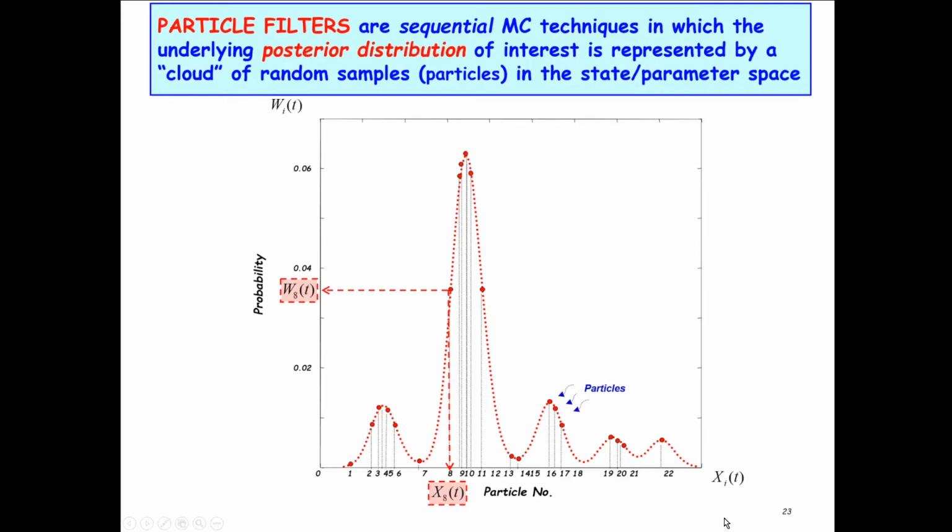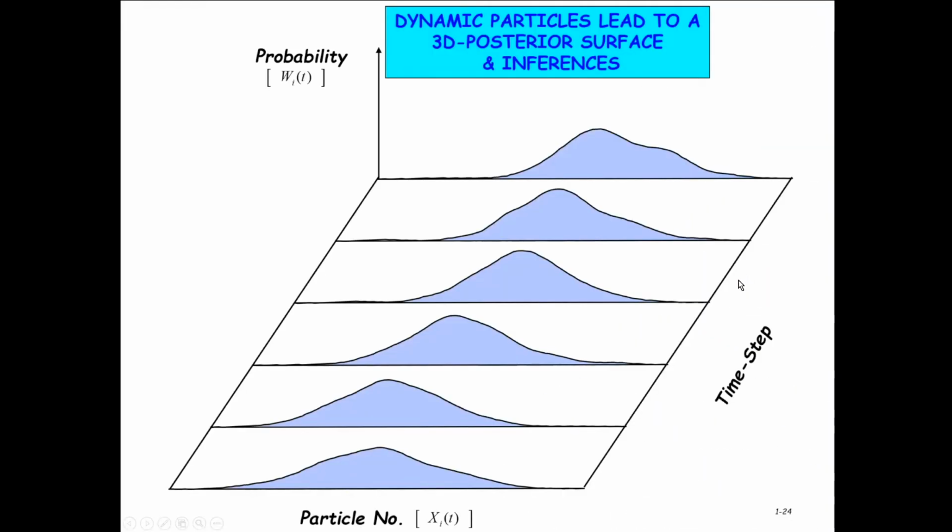Now notice another thing, this is just one sample in time. So if you think of a time series, this is what makes it different from the standard signal processing that we're used to, where we're given a set of data and we build a filter in some part of the frequency domain to eliminate or to enhance the signal. In this case, this is just one time sample, or this can be a vector if it's a multi-channel system. So the particle filter at this point in time has estimated an empirical distribution. So it's a probability mass function, and the W's can be thought of as probabilities. So think of it that way. But we don't have just that. We have a whole bunch of time steps in a time series, and that's what we're seeing here. So the particle filter at each point in time is estimating the associated posterior probability. So if I have 10 samples, I've got 10 distributions.